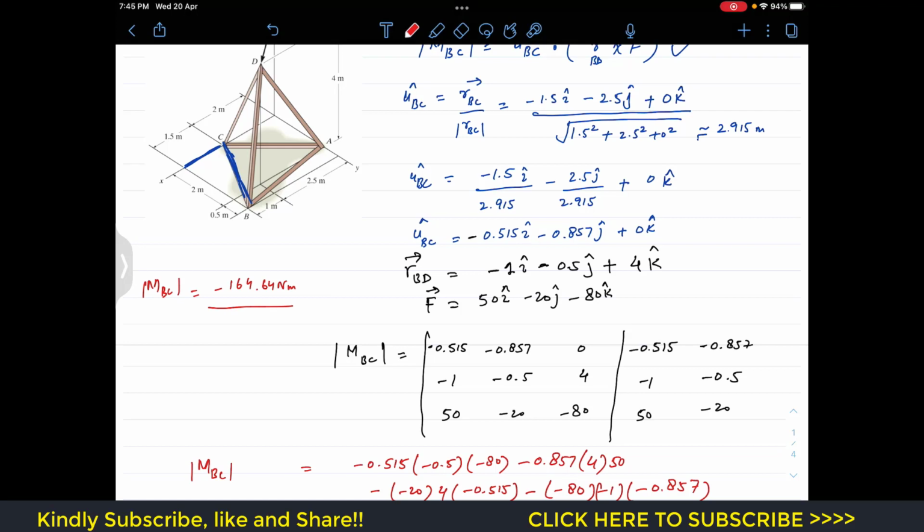Newton meter. So now the negative sign tells us that the moment is in the opposite direction of the unit vector. The unit vector is from B to C, and the moment produced is in the opposite direction of B to C. And now if we direct our thumb in the direction of this C to B, in the direction of the moment, and if we curl our right hand fingers, that will give us the direction of the moment about that BC line.